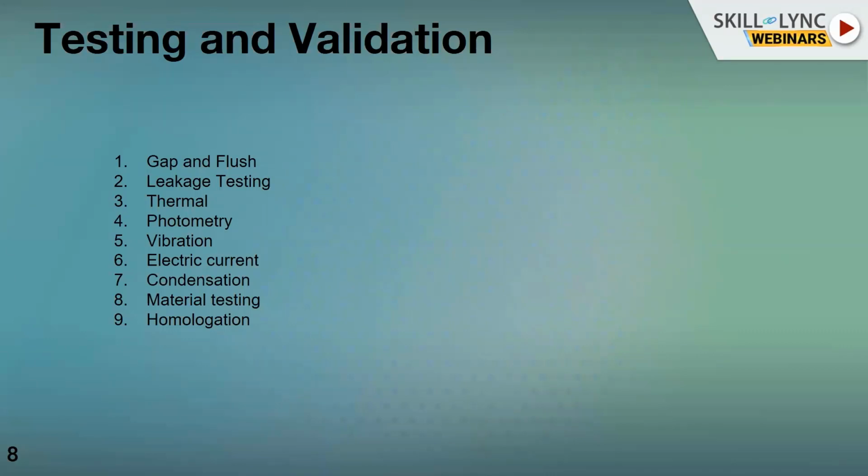The fourth one is the photometry, and this is the very essential and crucial part, because the regulation we discussed checks the photometry of your lamp, and your requirement should be fulfilled, right? Like if we are having the 1A category of the front side lamp of the indicator, then it should meet the 400 candela, and it should be not more than the 1200 candela.